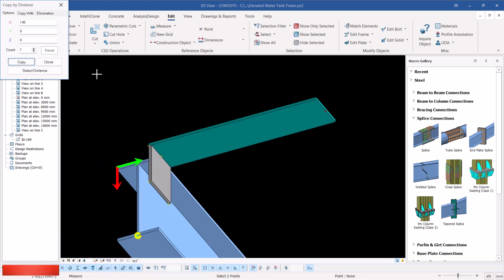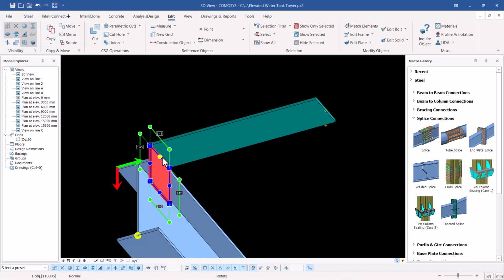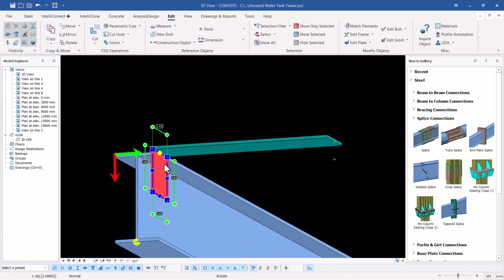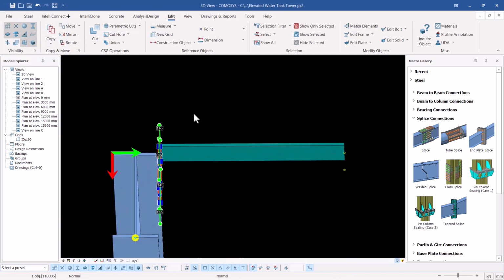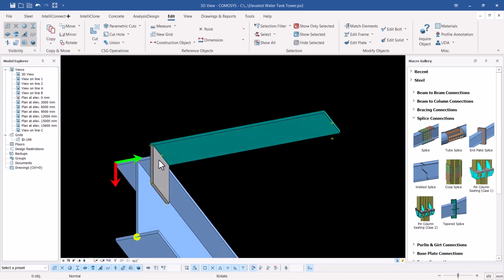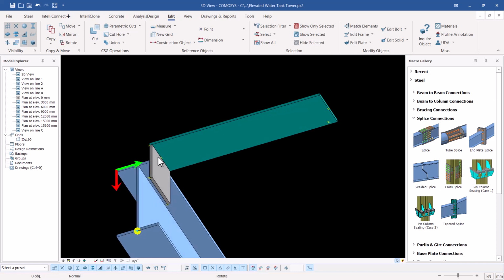And I want to bring it down by 60 millimeter. So on the x-axis, I'll feed in 60 millimeter and take it down like that. So if I close this and select on that section and right click and hold and move my mouse like that, I'll be able to rotate it accurately. So let me put it in a position that I'll be able to rotate it accurately.